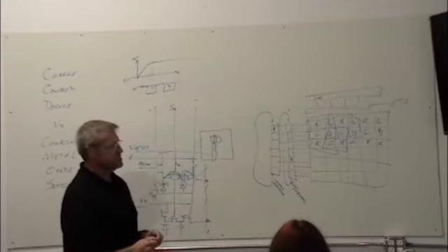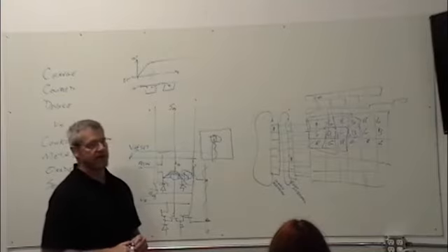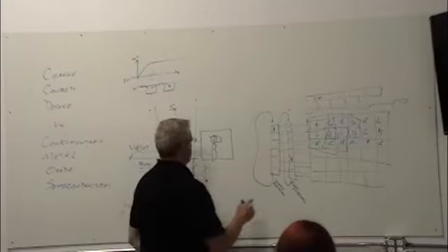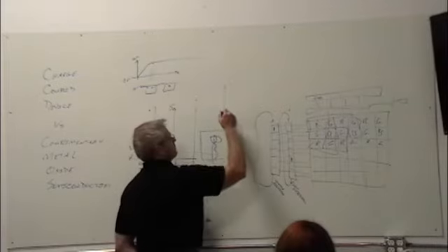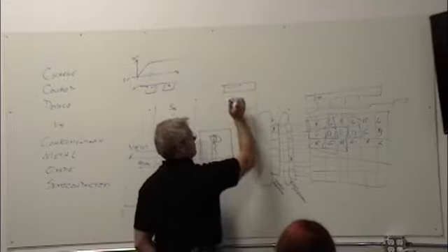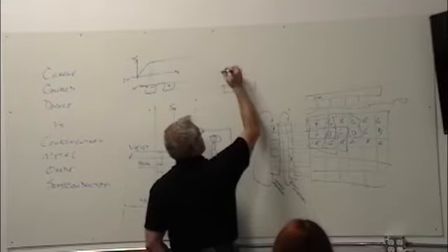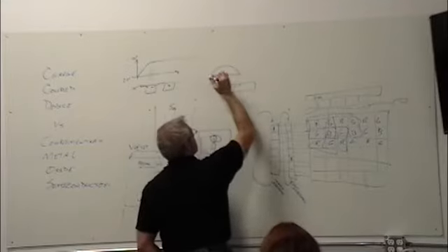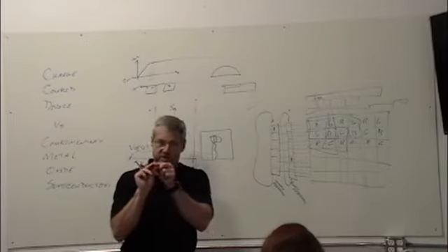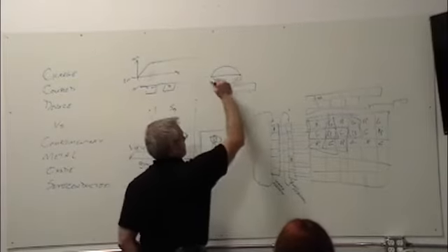What you'll also see, almost every imager now, they have micro lenses on them. So we talked about this X% fill factor, right? I've only got this much of it being used. They've come up with processes where they've actually managed to put a lens on top that's only 8 microns or whatever it is, but it focuses all the light down like this. And they figured out how to do that.